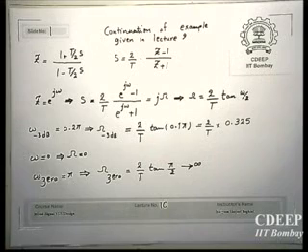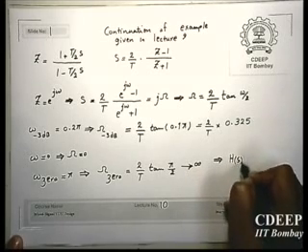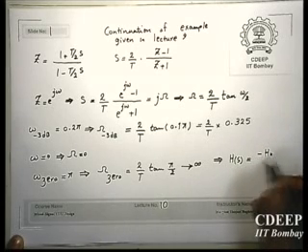Now this is interesting because if you have a 0 at s equal to infinity, this means that you don't have any explicit value. It is just enough to have the denominator one order more than the numerator. Then automatically you will get a 0 at s equal to infinity. Therefore, in the S domain, your transfer function will be just first order without any 0 in the numerator.